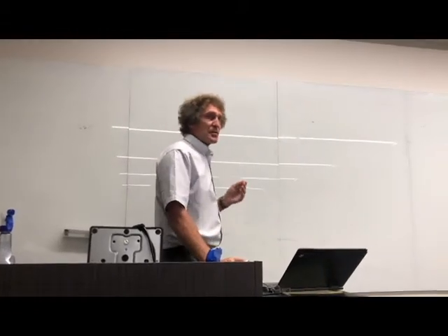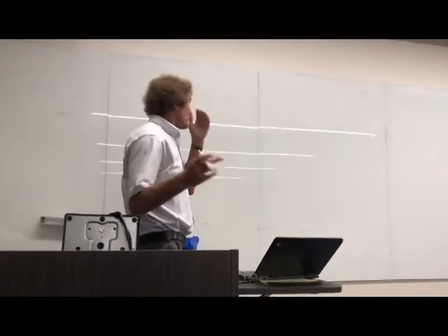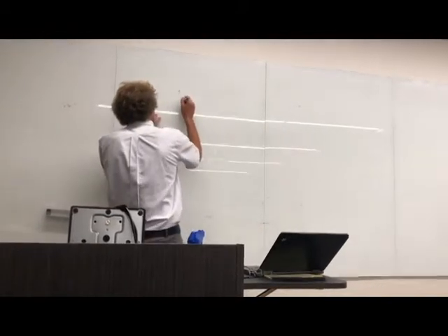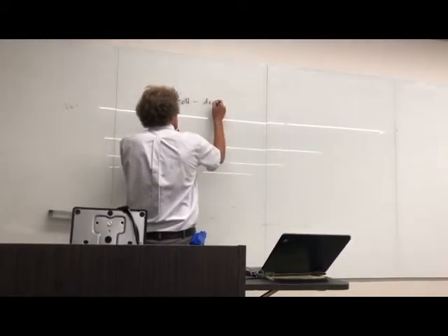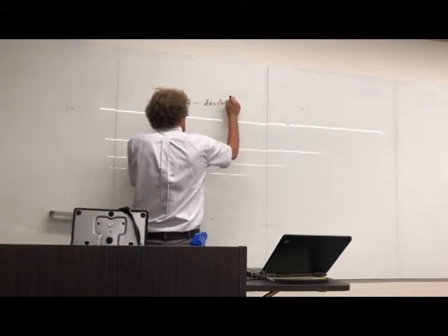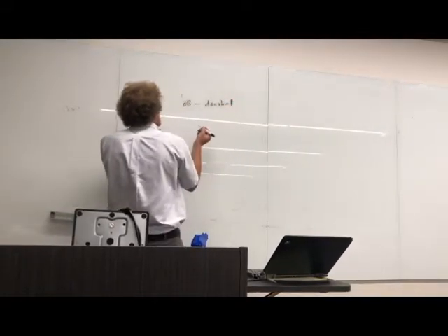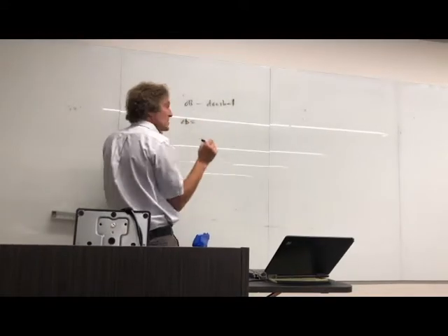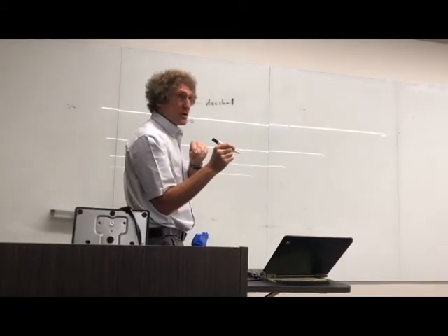It's real important. In engineering, many times we deal with things that are 10 or 12 orders of magnitude in difference. And it's insane to talk about the ratios when they have 10 to the minus 10th, or really a 10 to the 10th scale. So we do it with decibels. Decibels is taking the log, really, of the number. So first, what is a dB? This is a decibel. It's named after a guy. And what a decibel is depends on if you're talking about voltage or current or power.